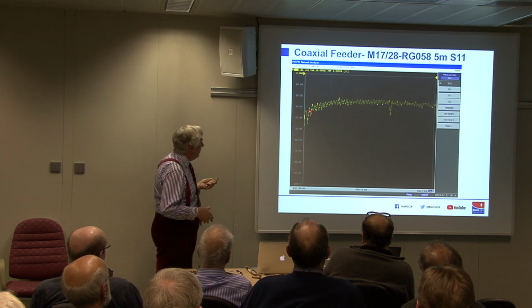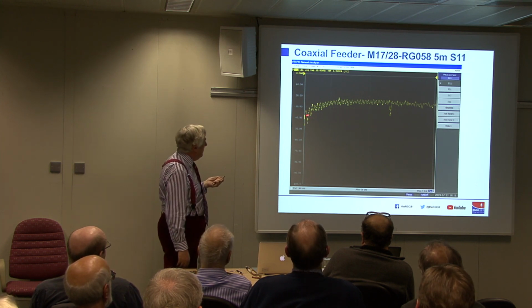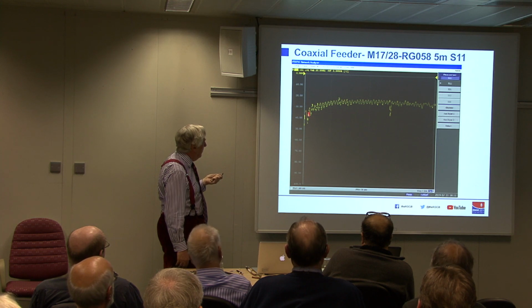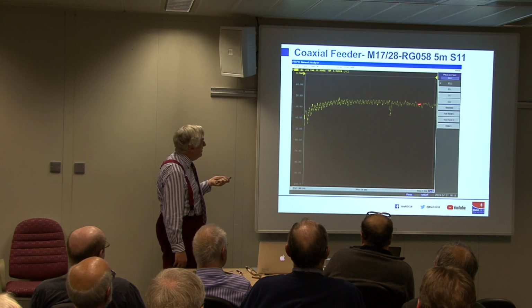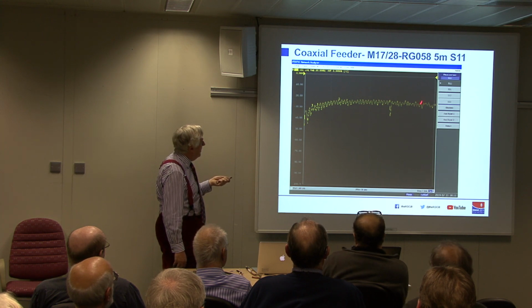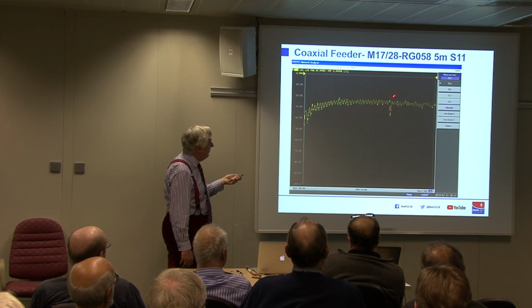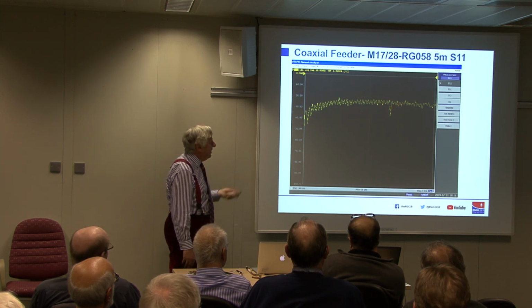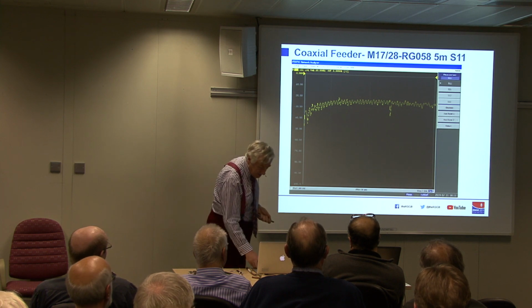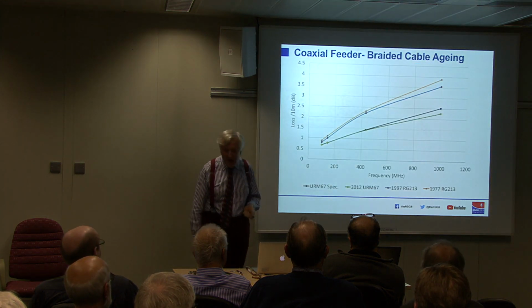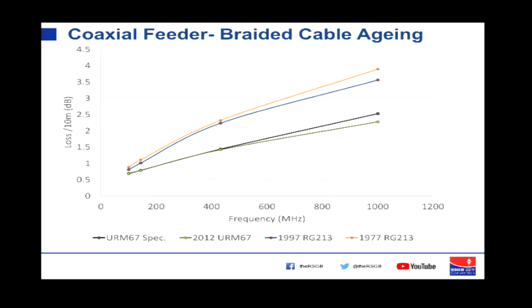The cable, actually, from being about minus 40 dB return loss at low VHF frequencies, this is not bad, this is a mil-spec piece of cable. It's about minus 25 return loss up, and with a little glitch in there, going up to 3 gigahertz. So do be careful if you use cables outside their rated frequency ranges. Then, oh yes, and this is the first of my hand-arounds.